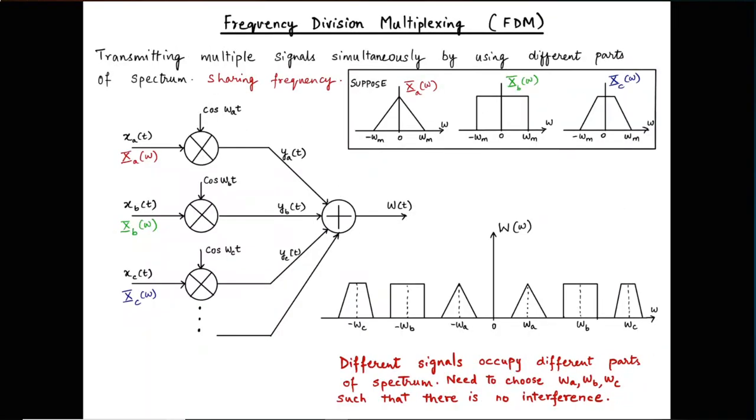Now to go to superheterodyne receiver and show you the benefits of doing it in 2 stages, we will start talking about frequency division multiplexing. And frequency division multiplexing is an idea in which we share the resource of frequency. We have talked about how FCC plays a role in the most expensive resource that is available to us, which is the frequency, the spectrum. So by sharing the frequency, we can transmit multiple signals at the same time. There are other forms of sharing as well.